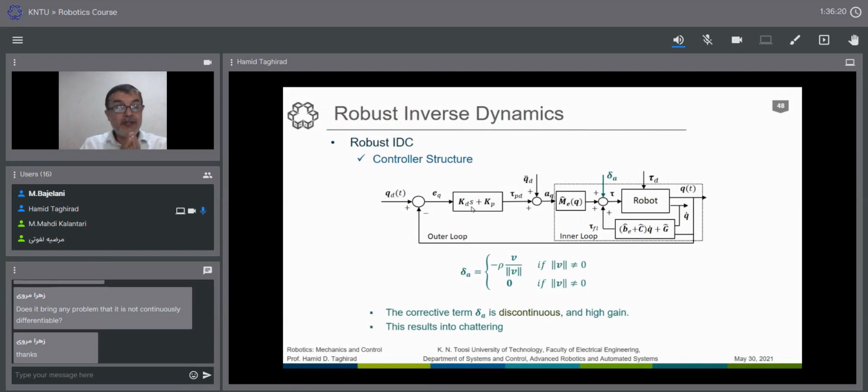Of course, usually we design a controller with a not very overcompensated actuator. If you have a robot with 10 kilogram payload, the motors are somehow 4 to 5 kilowatts. Of course, you can use 10 kilowatts there, then you have a much higher gain, but it is not very economical to design like that.